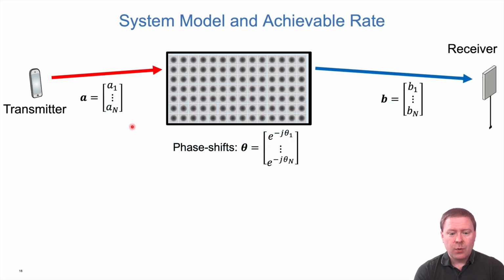So with this in mind now, how can we optimize the RIS and how can we do channel estimation? We can study this as just one frequency because we have this line of sight like path. Suppose the transmitter sends a signal to the RIS, there are N elements in the RIS, well then there are channel coefficients A1 to AN describing those channels. Each of the elements has a phase shift that it is generating. I have the theta here that is describing those phase shifts, and then from each element to the receiver there is a coefficient B1 to BN for different elements describing the channel.